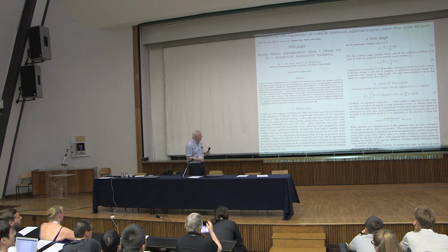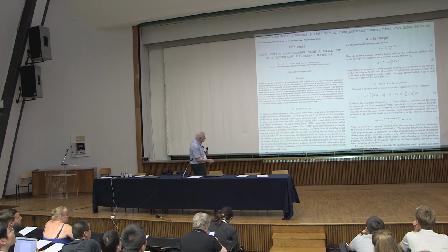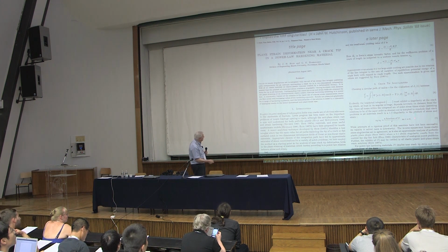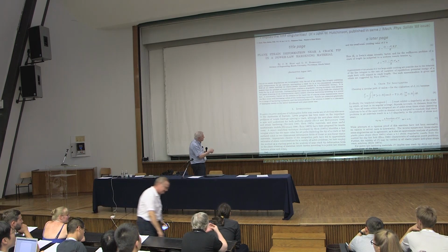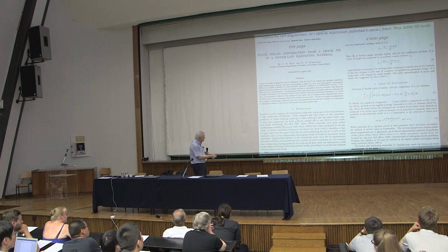And so we ended up both at the same place in getting these so-called HRR fields, and their property is that the product of stress and strain is an angularly dependent term divided by distance from the crack tip, at least asymptotically as the distance from the crack tip goes to zero. So these were the HRR fields, and their existence and properties just followed at once from the J integral, though as I said, John got there from a separate route.